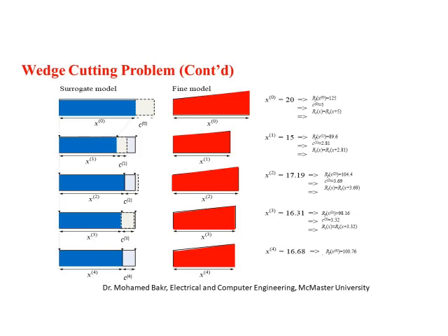Let's follow the steps of what's happening here. We started with 20. This is the optimal coarse model design, and it gives me an area of 100. We give this to the fine model, and it gives us 125. Something here is not right, because we are getting higher than what we are expecting. So we ask ourselves how we should correct the input parameters to the coarse model to get this area of 125. This is called parameter extraction.